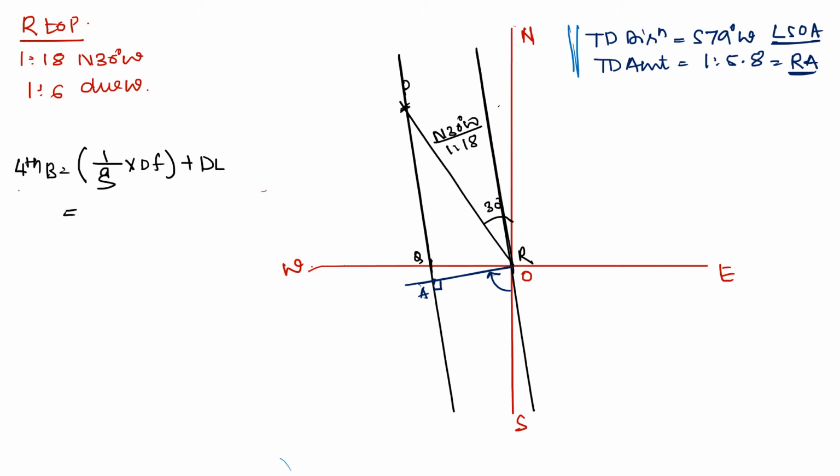So first we need to calculate the gradient. Now where is the fourth borehole located? It is located north 60 west. So let us plot north 60 west first. I'll take this north 60. Say this is 45 around, and this comes to be 60, and that point is named as S.